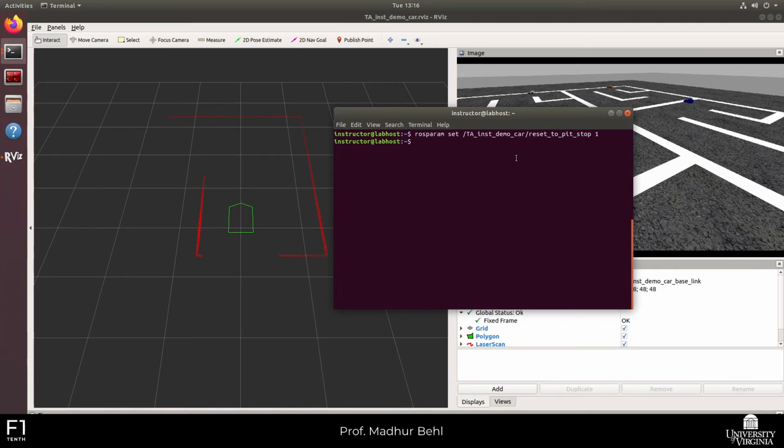So let's jump into what you may want to do after you have SSH'd. If you look at the current directory structure in your account, you will see the Catkin workspace has already been created. In fact, this has some nodes which you use for teleop during the lab session for the simulator. So what we will do is first pull the race package into the Catkin workspace in the simulation account assigned for your team.